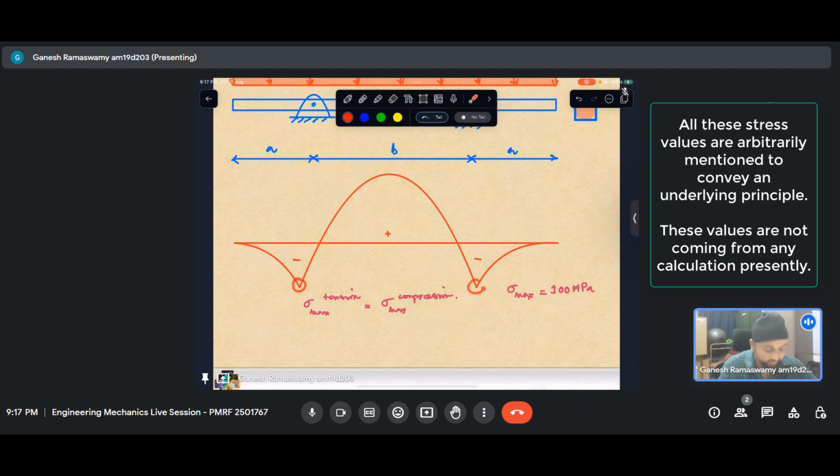And at these 2 points, it will reach somewhere around 30. At the same time, if I reduce this to a much lower extent, that is, if I increase the overhang, in such a case, I'll notice that the peaks at the negative bending moment side, the stress will peak to around 90, and at the tension side, it will just barely be hovering around 20.